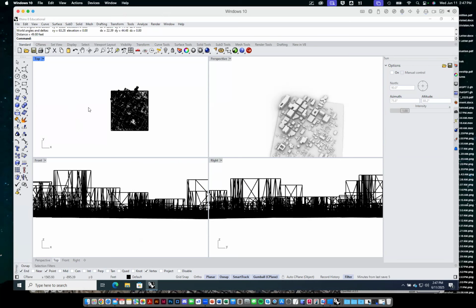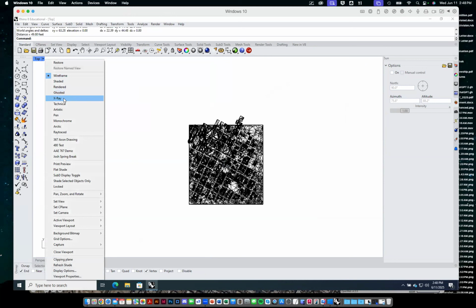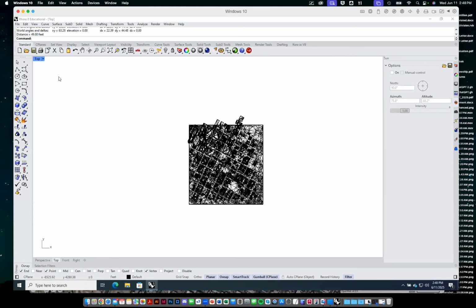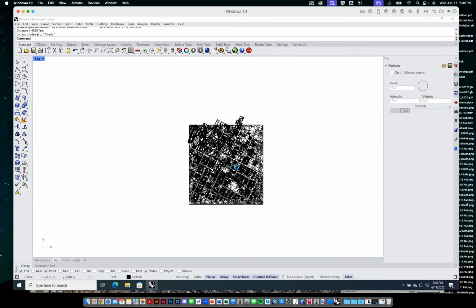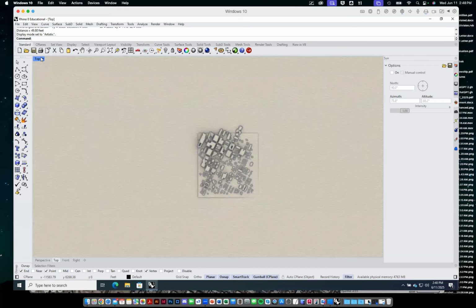What function did you use to scale the entire thing? I just typed in scale. Oh, okay. Yeah, it's just scale. Rotate, move, and scale. They're all just type them in. Copy, same thing, COPY. Type them in the command line. It's a good question. And again, I don't realize sometimes I take these things for granted. So please do ask, speak up and ask, and happy to.